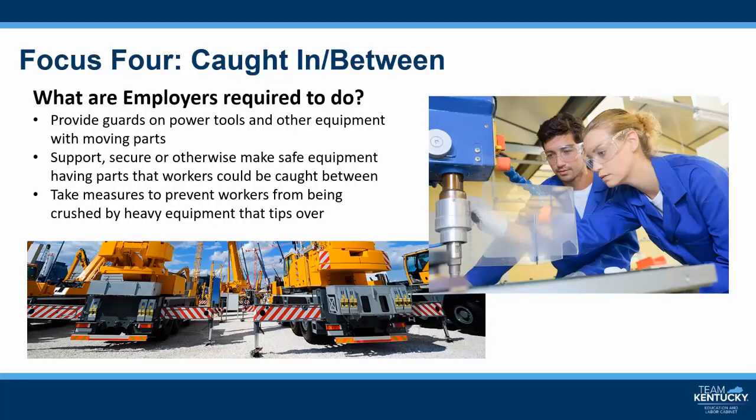The employer should provide a lockout-tagout program or equivalent system to ensure that the equipment is not accidentally energized during maintenance or repair. Lockout-tagout procedures are specifically required for equipment used in concrete and masonry operations. Bulldozer and scraper blades, end loader buckets, dump bodies, and similar equipment must be fully blocked or fully lowered when being repaired or not in use.